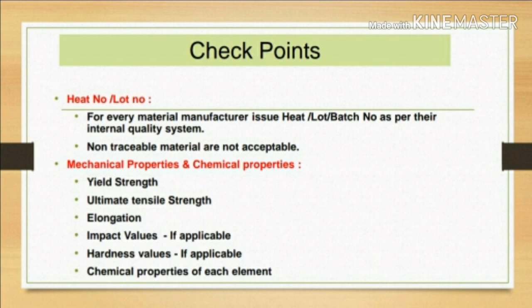During review, one has to take care that the sample drawn direction needs to be verified, because generally these preferable directions are mentioned in the material specification and we have to check whether they are followed in the MTC or not. If it is not followed, then we have to simply reject the material. Generally longitudinal or transverse directions are mentioned in the material specification.